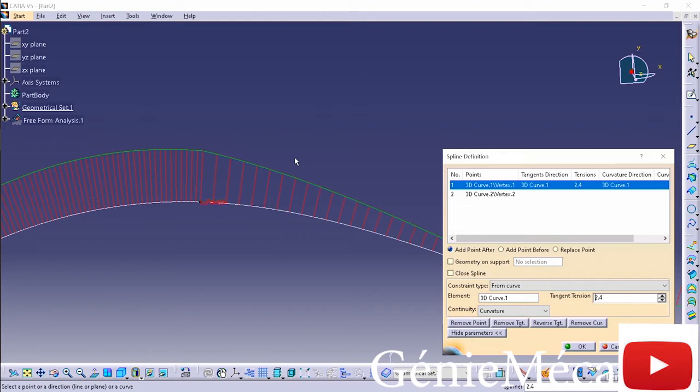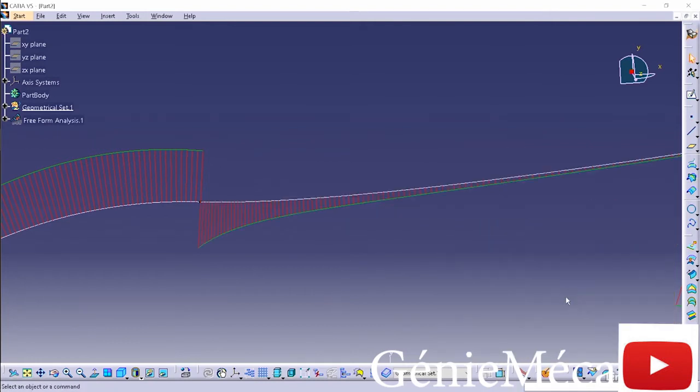And again, you can get away with using a conic. Even though it may not be perfectly G2, it sort of fakes the G2 condition. So as you're designing things, it's very important to always consider what's happening to the shape of that curve and that continuity.